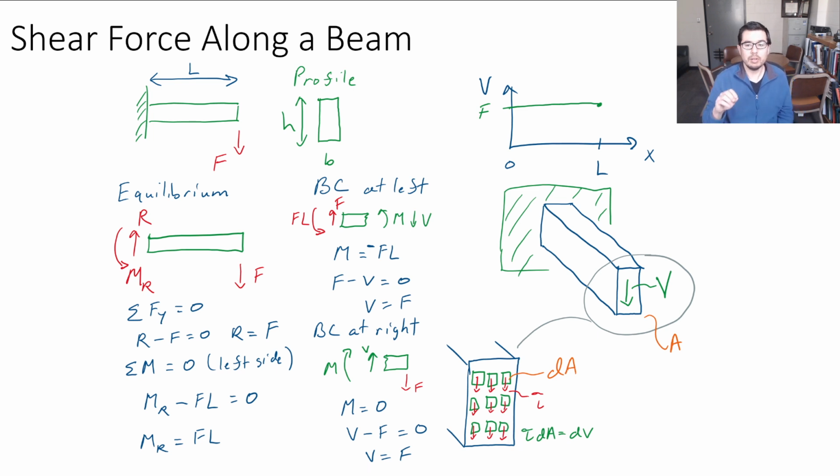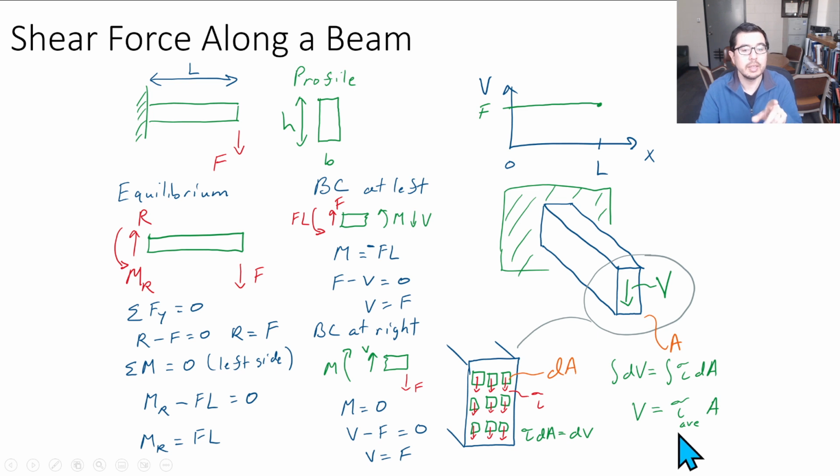We might also be wondering, this shear stress is acting on the face that's been cut. This is orthogonal to that transverse shear stress that we said was acting along the beam. Well, we're going to get there and discuss that in just a second. But first, what we can say is that there's an equivalent average shear stress related to the shear force and the area. This is commonly written as tau_av equals V over A.